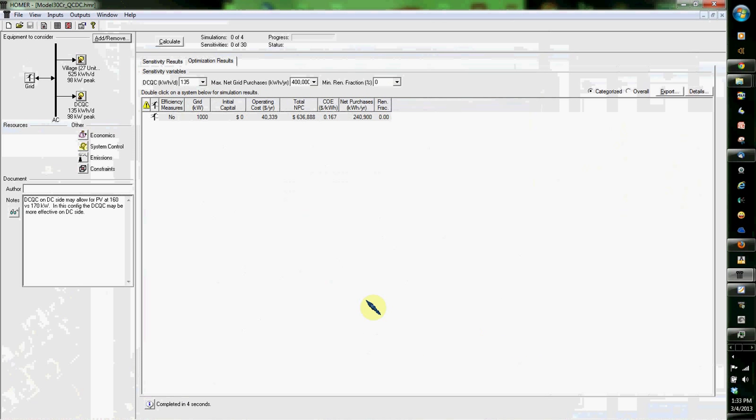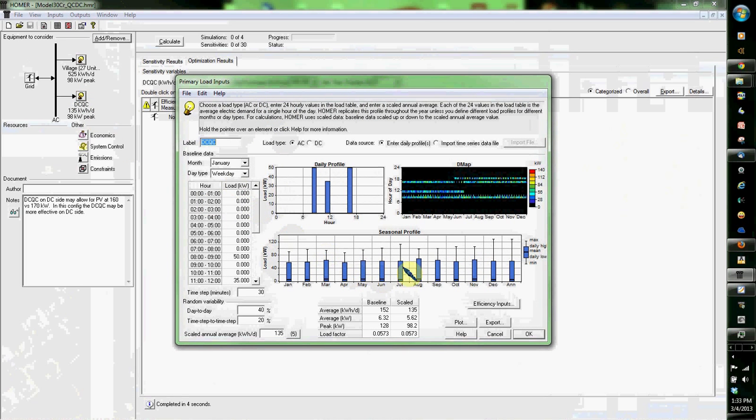So what I added is another load, and I call this my electric vehicle DC quick charger, as you see there. In this case, it is currently AC, later it will be DC, and I did that for a reason. There are 27 units I was using. I assumed 2 cars per unit and 10% population for EVs. So 5.4, which basically works out at 10%.